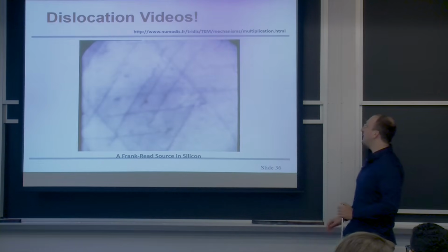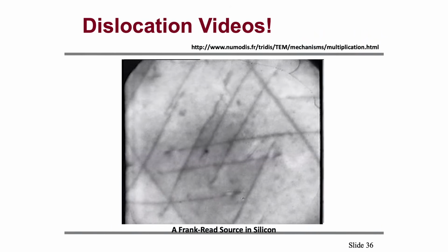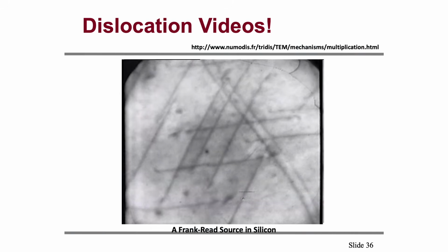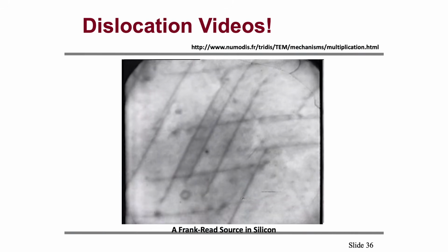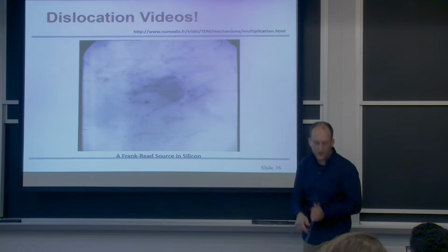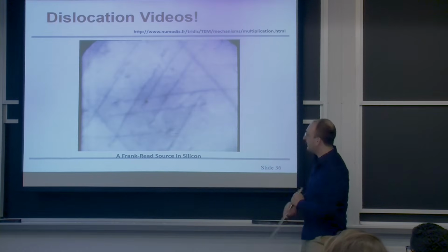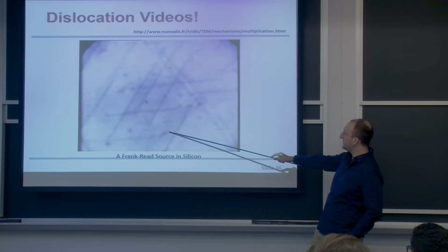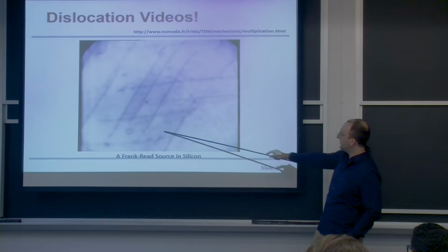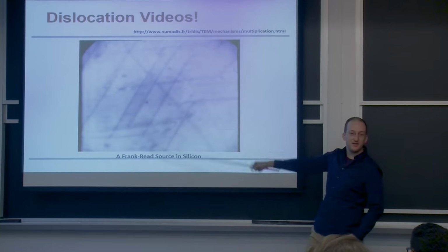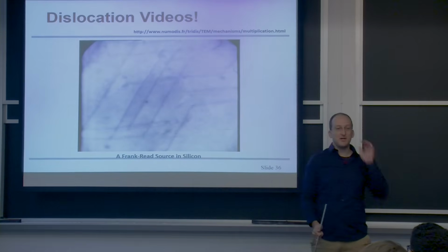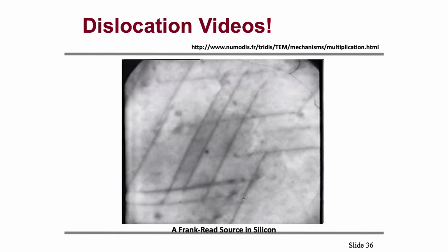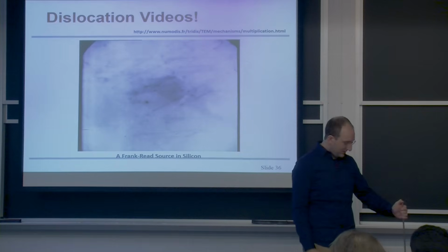There's another one, what we call a Frank-Read source. It's a source of dislocation loops. So what you're seeing here, each of these lines is a single dislocation. And then right there, you see that loop suddenly form? Let's show you that one again. I'll point out where to look. By stressing out materials, you can actually create additional dislocation loops right around here. And there it is. You guys see that one? Yeah. Out of what looks like nothing, but is actually just a couple of atomic defects, you can create a dislocation loop and allow more plastic deformation to take place, which I think is awesome.